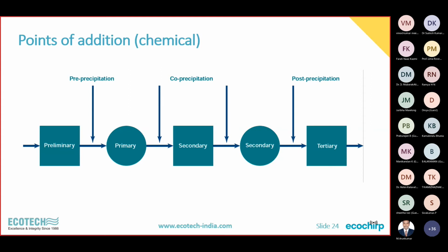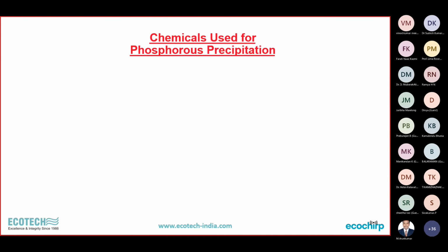In this particular case, phosphorus removal, no such additional physical infrastructure is required. It is only providing a dosing tank, maybe a dosing pump. That's it. Overnight, we can implement a phosphorus removal strategy, unlike the denitrification stage.